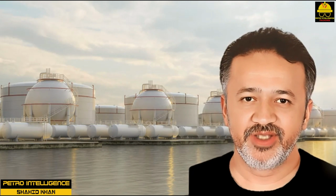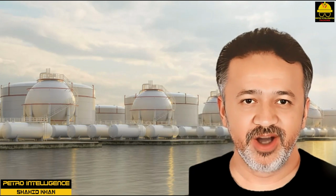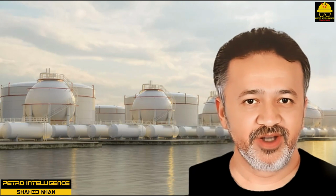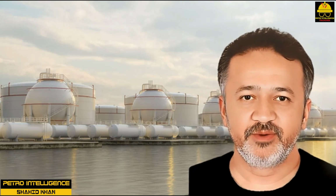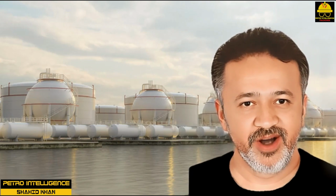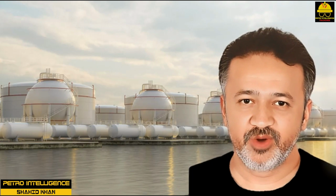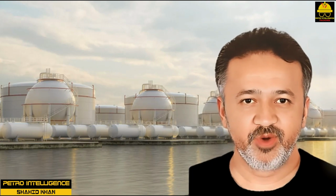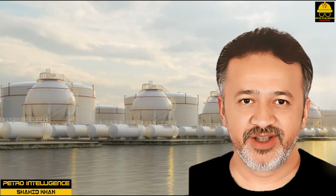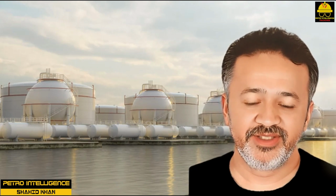Temperature. In general, the strength of metals decreases as temperature increases. Reduction in strength usually starts at 650 degrees Fahrenheit or 343.33 degrees Celsius and becomes critical in the range of 950 degrees Fahrenheit or 510 degrees Celsius to 1000 degrees Fahrenheit or 537.55 degrees Celsius in the case of carbon steel. For example, the strength of low-carbon steel is reduced 22% when temperature is raised from 950 degrees Fahrenheit to 975 degrees Fahrenheit, or 510 degrees Celsius to 523.88 degrees Celsius.